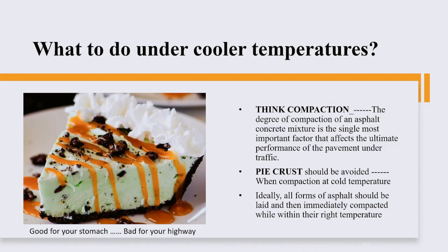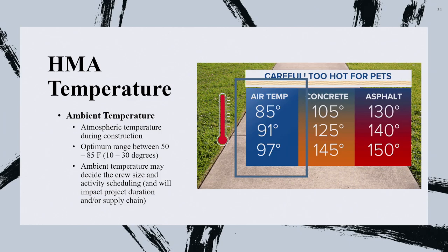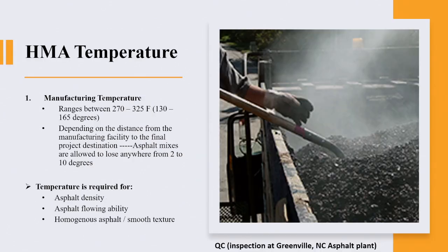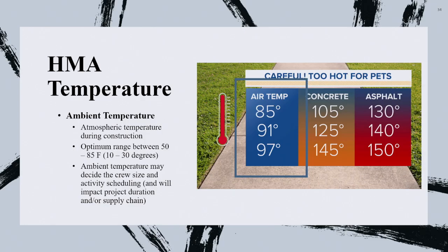If you remember when I talked in the second presentation, right before lunch, poor compaction would result in ruts. So this is a huge outcome if the temperature was not monitored, if you allow a drop greater than 10 degrees. Now, one thing you can do, and that's what we are tremendously using in the US, is shift to warm mix asphalt.